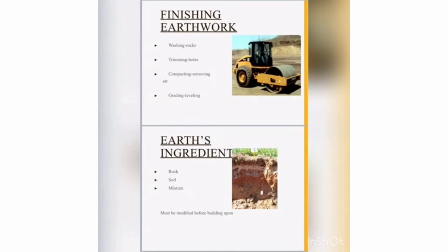Third, mixture. Mixing concrete is simply defined as the complete blending of the materials which are required for the production of homogeneous concrete. A successful mixture cannot be achieved without the proper batching of all materials. Batching is the process of weighing or volumetrically measuring and introducing into the mixer the ingredients for a batch of concrete.